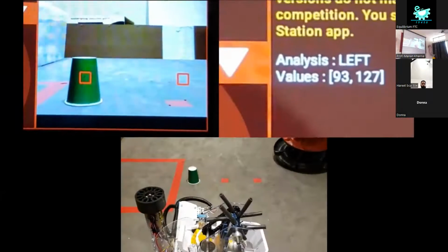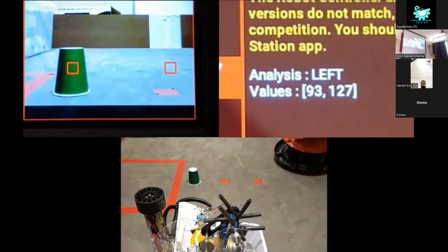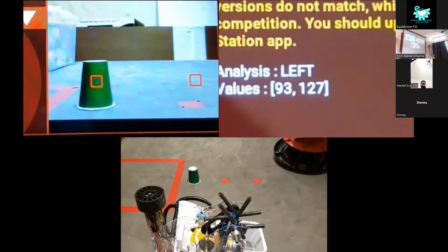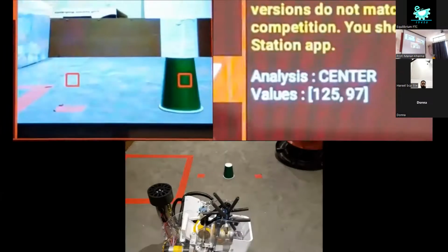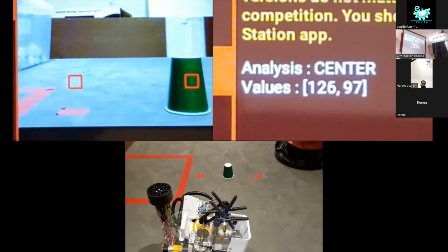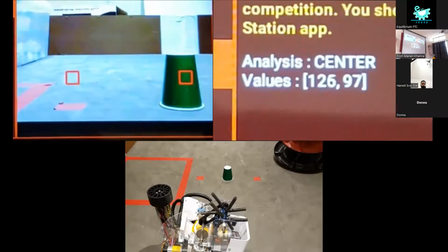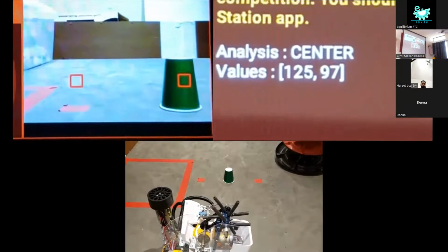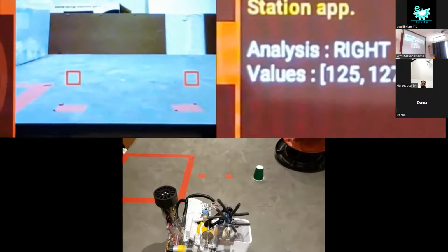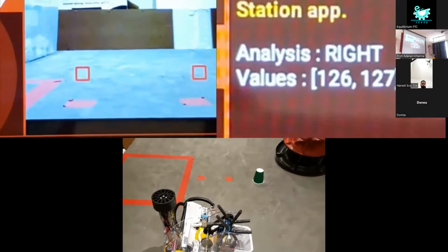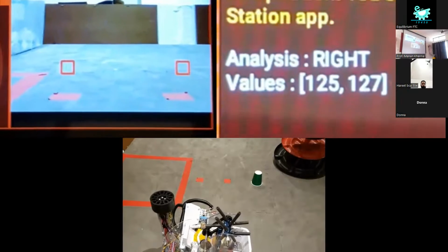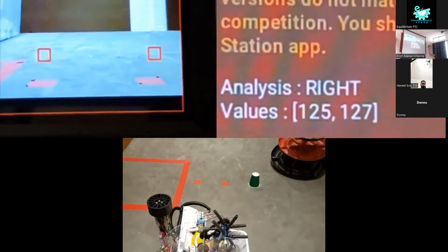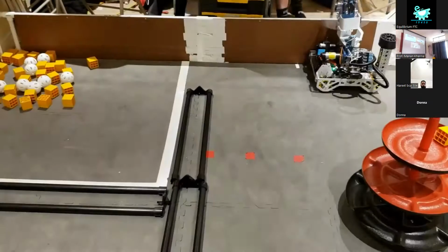At the beginning of Autonomous, the robot uses OpenCV pipelines to automatically determine the position of our custom team shipping element on the field, scoring bonus points for delivering freight to the corresponding level of the Alliance shipping hub. The robot performs a comparison on color values contained within the highlighted red boxes on the camera site to accurately determine the position of the team shipping element by measuring the average color distance from the color red. Our team shipping element is colored green to accentuate this effect.